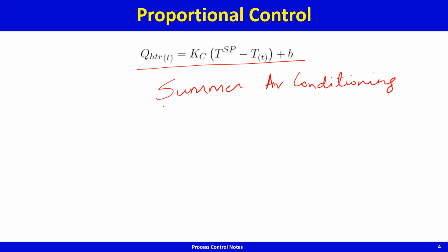Now the air conditioning power, or now you have these inverter ACs, what is the speed at which the compressor rotates? If you want more cooling, the compressor must rotate at a higher speed. If you want less cooling, the compressor rotates at a lower speed. So in these inverter air conditioners, you would have Q cooling, C for cooling.